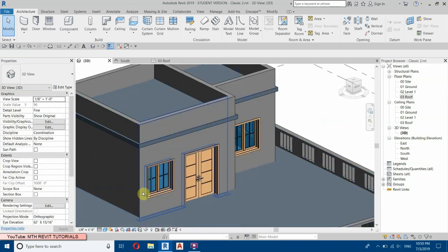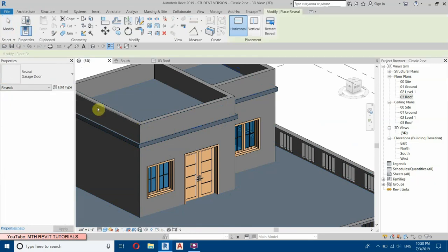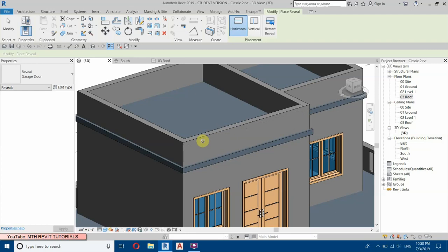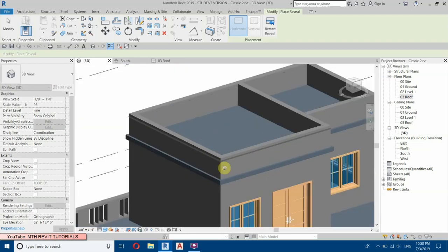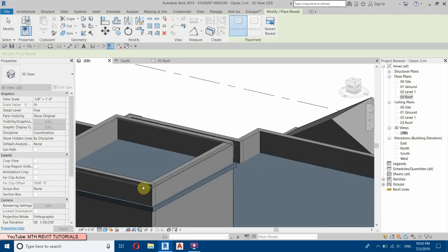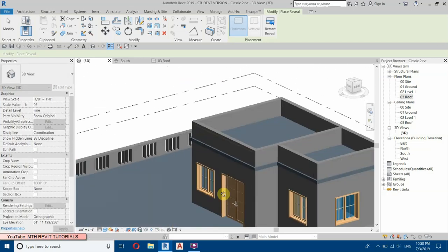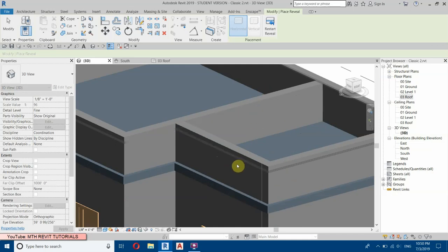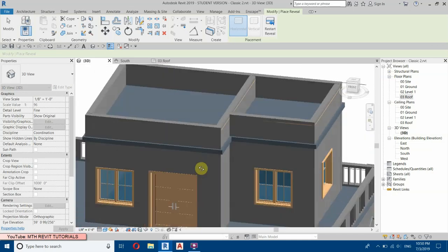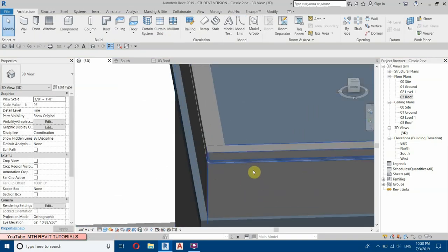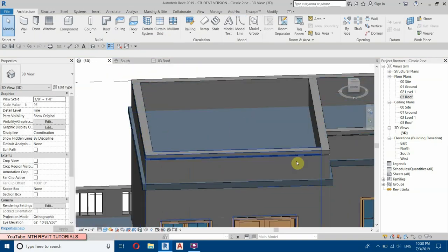Let's create the wall reveals here. So you will find that in this drop down, select wall reveal, then garage door. This 1 inch wall reveal we have created for the garage door, if you remember, in the second part of this tutorial series. So now I will just cancel, and you can see we got a void here. We got this reveal here.